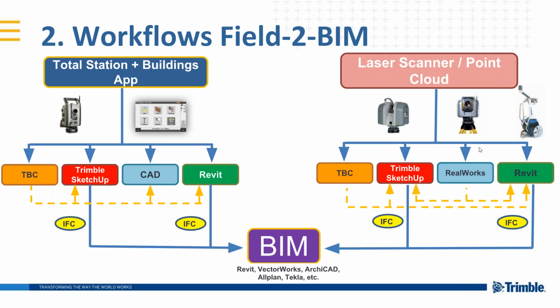But we could also import the point cloud inside RealWorks, Trimble RealWorks, so we can also create very highly detailed 3D models, even in real time, connected to SketchUp. So we can click on points on the wall, and the wall is created in real time on the right side inside SketchUp. So there are different ways that we can follow. Therefore we try to summarize the ways that you could use, and I hope that you identify yourself in some of these workflows. So we will see some of them right now.